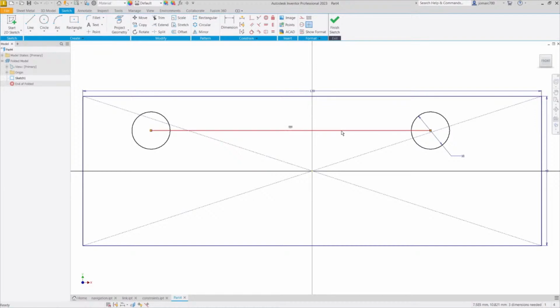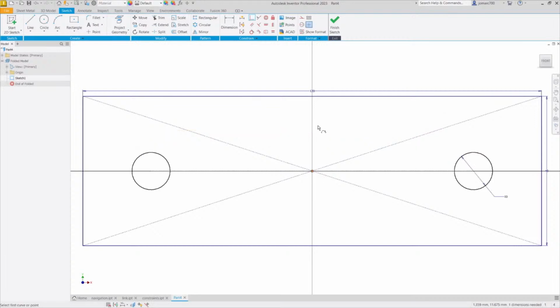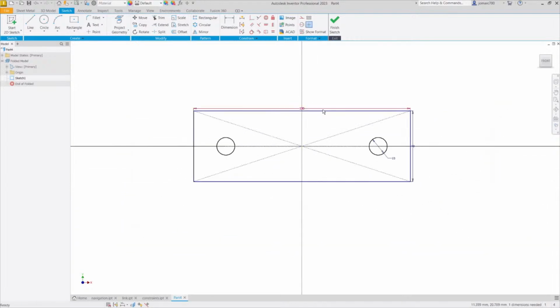and this line once more serves as a construction tool. Selecting this line, let's right click, selecting construction, and finally let's head up, selecting coincident, looking for the midpoint of this horizontal construction line, which is this green dot. Left click and selecting our origin. Left click, hitting escape, and let's inspect. Notice the color, which means this is fully defined.